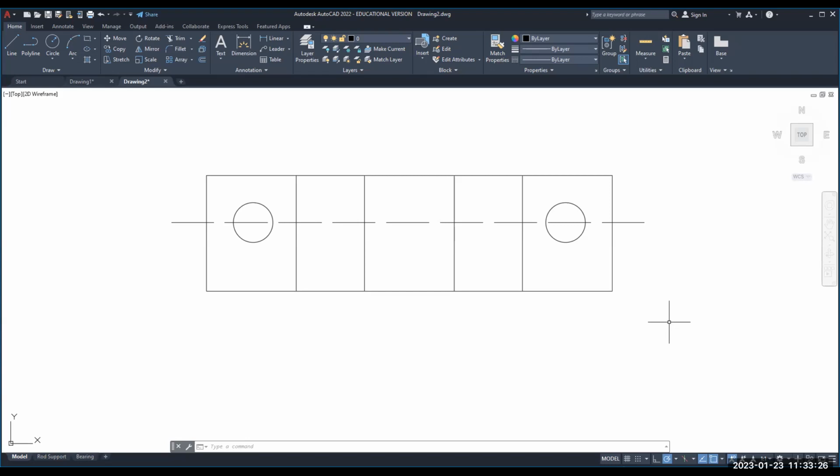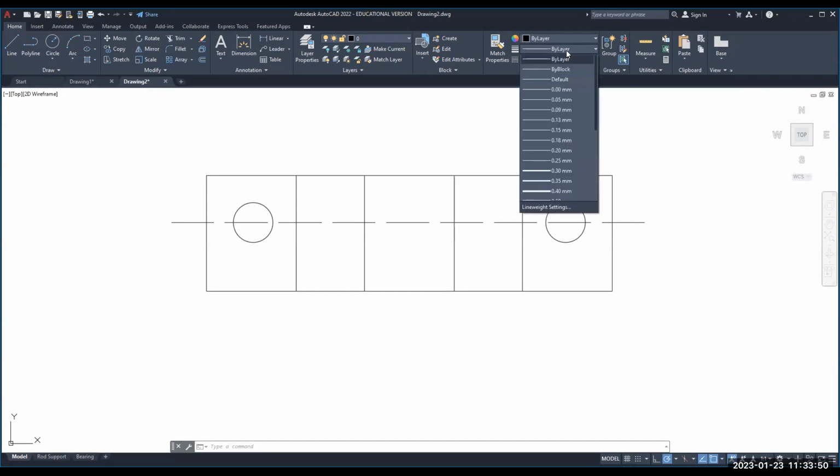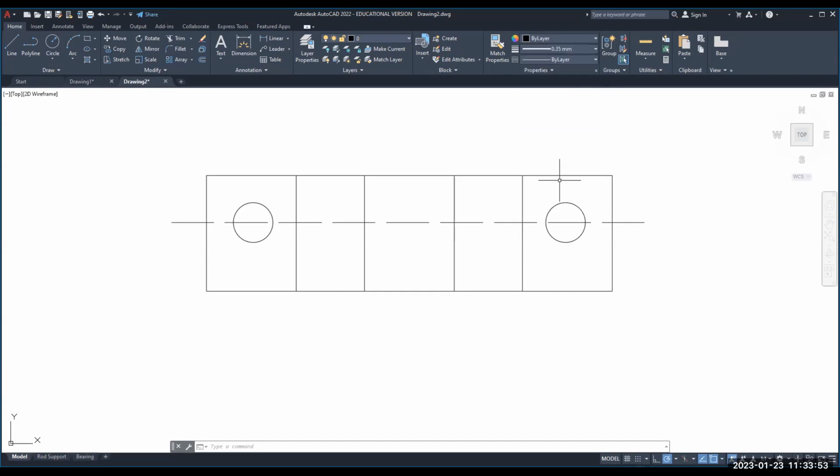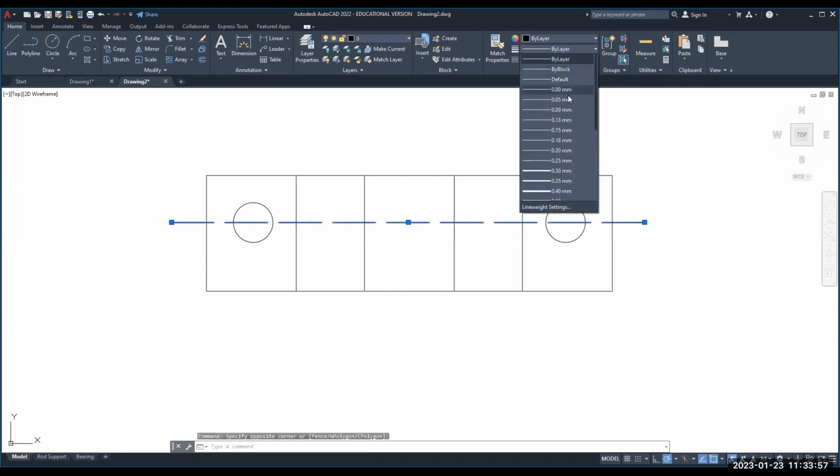You can put that cutting plane anywhere you want. Like if there was more geometry here, you can actually offset the cutting plane line. That's called an offset section. We're not doing that. We're just doing straight cuts, but you can pick up any geometry you want. So I want these circles. Then I can give this line thickness because it's supposed to be a good thick line. That's here. I'll just go down to 0.35.